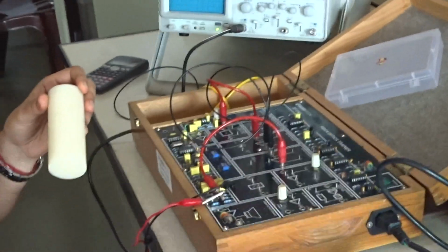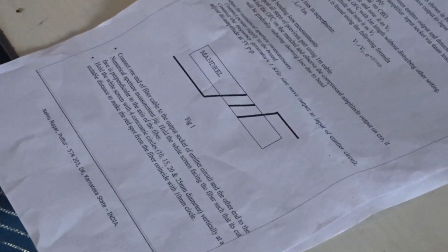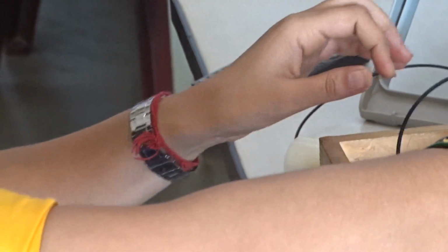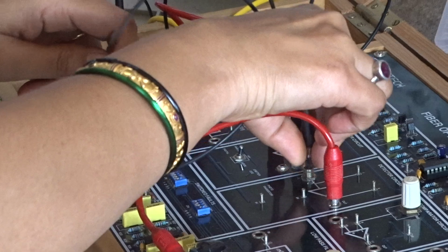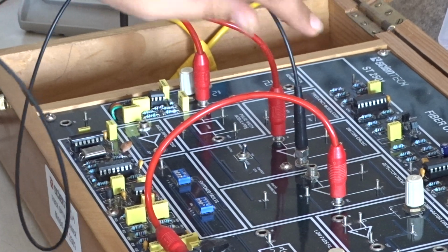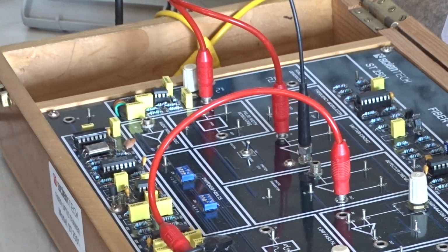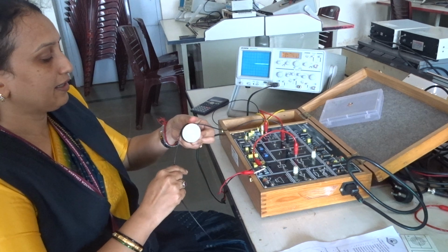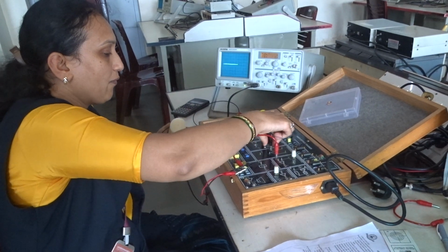Second part of the experiment, we need to calculate the bending loss. Bending loss will be calculated by rotating the 1 meter cable around the mandrel, so that as you decrease the radius of curvature and increase the number of turns, the losses will increase. Let us do the experiment using the 1 meter cable. I am not changing any setting of this connection. I have taken the 1 meter cable and we need to rotate it over a mandrel. I will rotate one turn and let us take the output voltage for one turn.